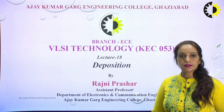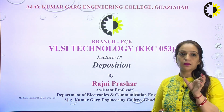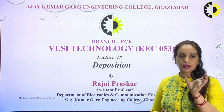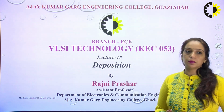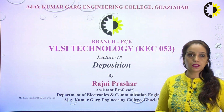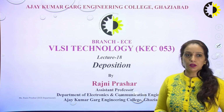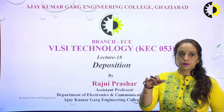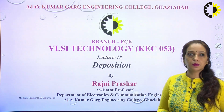So in the previous lecture we have seen that with the help of the photolithography process we have created one window, and over that window we have to diffuse some of the dopants, right. After that, when we created the window where we have to dope, with the help of the etching process we removed the silicon dioxide so that we can come in contact with the silicon wafer, where we have to diffuse some dopants. Now before diffusion we have to deposit some of the material over the substrate, which is used for the further processing steps.